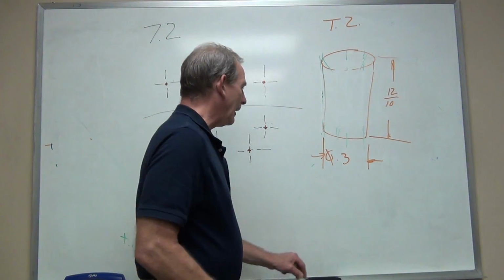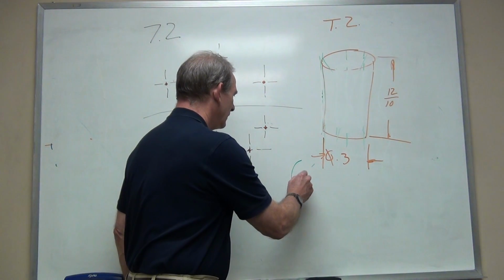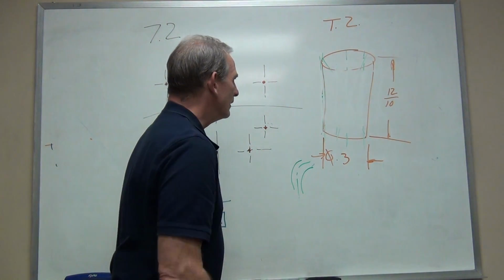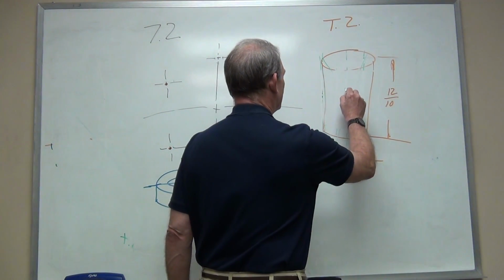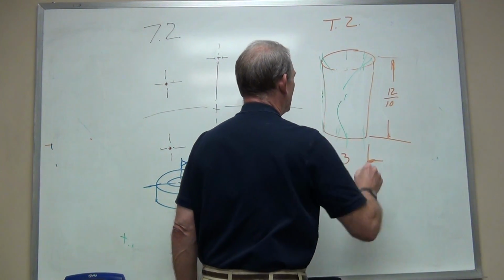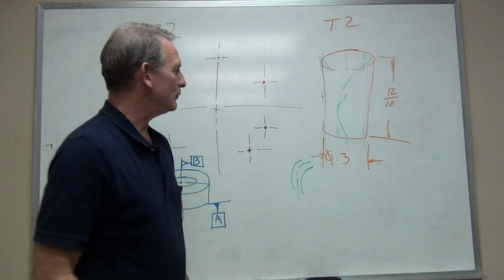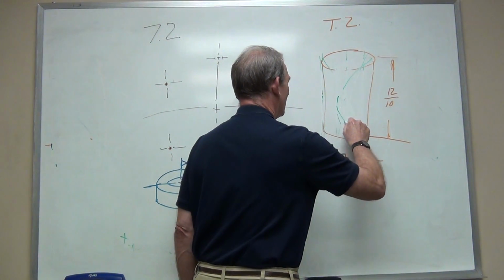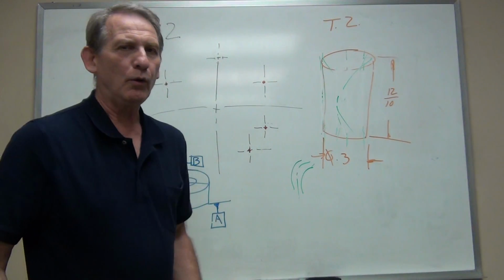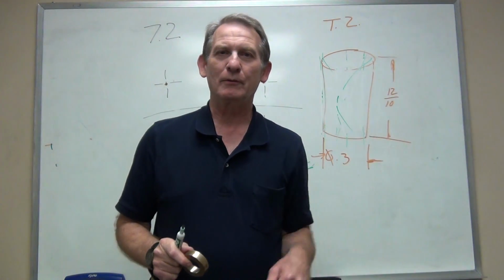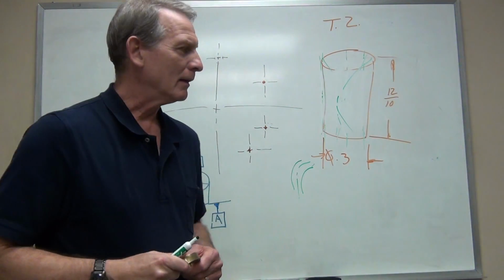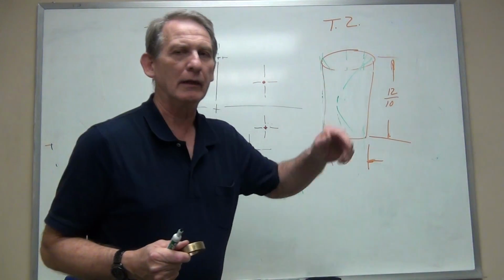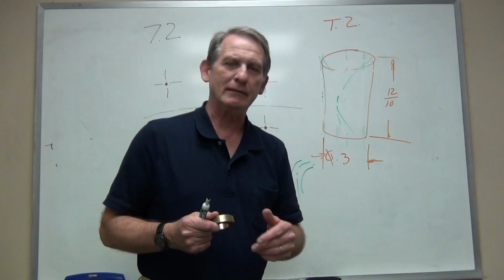It could be a curved hole, as long as the center line of that feature fits within that tolerance zone. I didn't do that very well, did I? That hole can be, let's say, bent or not straight because there is no straightness control. The tolerance zone for the orientation or the position has to take care of that.